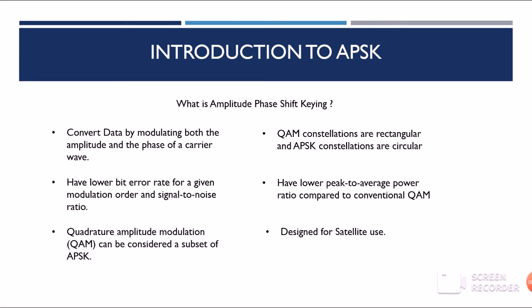The advantage of APSK over conventional QAM is a lower number of possible amplitude levels and therefore a lower peak to average power ratio. The resilience of APSK to amplifier and channel non-linearities afforded by its low PAPR have made it especially attractive for satellite communication.